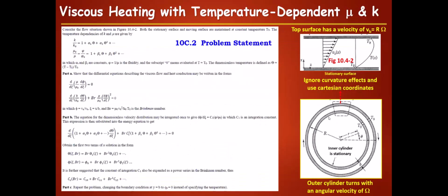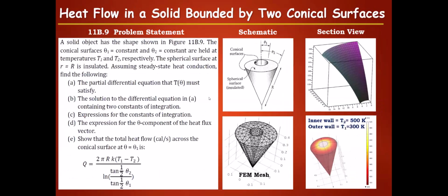So an example of this might be this problem shown here, where we have a rotating type of viscometer, and what we want to do is basically be able to predict the temperature profile of the energy that occurs by viscous dissipation, which is caused by velocity gradients. We want to be able to couple that with the momentum balance.